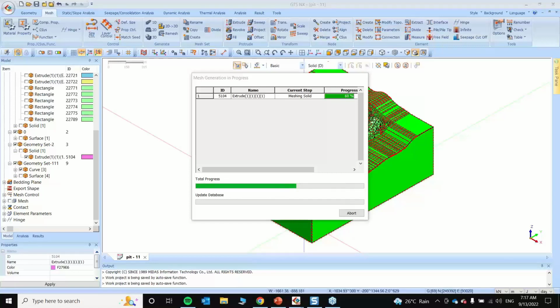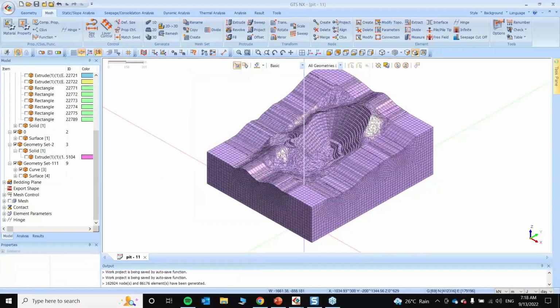So I have a question from Mr. Shovan: while incorporating the SRM method, how does the factor of 1.9 come up? See, when we employ the SRM method, the software does all the iterations. It's an iterative method. So the software reduces the strength parameters, the cohesion and friction, by a predefined margin, that was 0.1. So the calculations will start from 1 until it will go to a factor where the model will reach divergence.